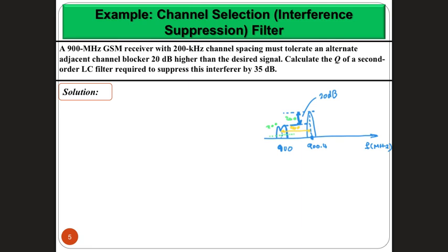So now I'm going to design my filter. Typically, the filter has to be flat within the frequency range of my signal, and then it starts dropping before and after, right? And the idea here is... I didn't draw this correctly, just to match the description. So let me do it in a better way. So here, that's flat during the signal, and then it starts dropping